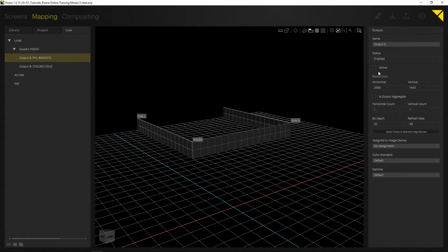By the way, I would highly recommend to never mix resolutions. I only do so here because here at home on my multi-monitor setup, I have 2 monitors with different resolutions. I would suggest to never do this in a live situation because mixing resolutions could, of course, result in tearing because the pixel clocks are vastly different. That's why please always try to avoid something like this.